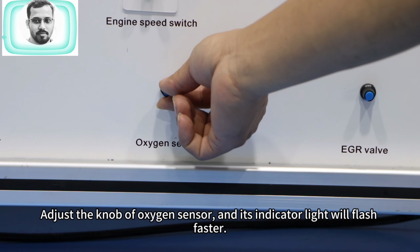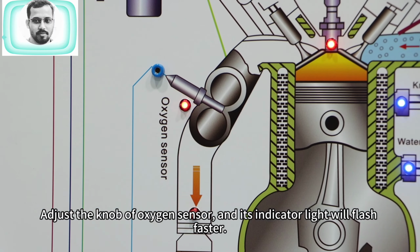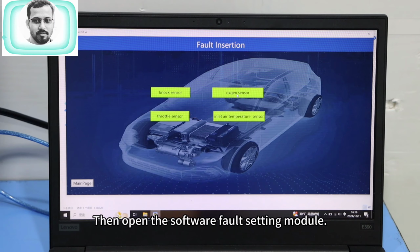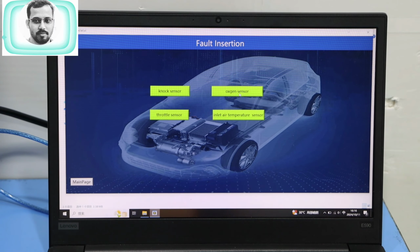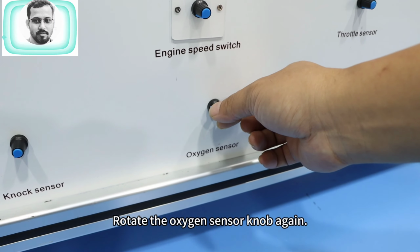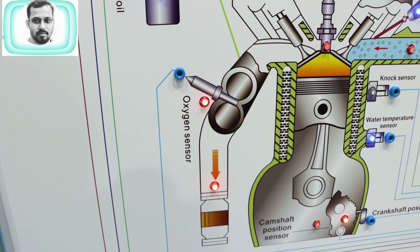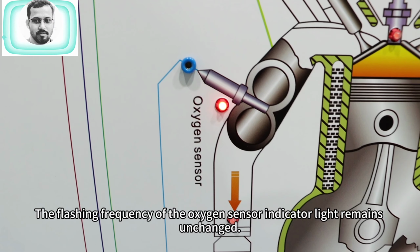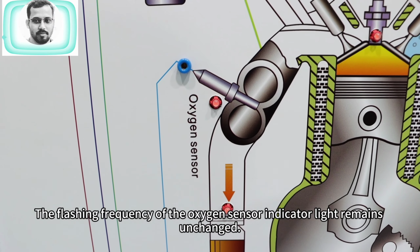Adjust the knob of the oxygen sensor and its indicator light will flash faster. Then open the software fault setting module. Set oxygen sensor fault. Rotate the oxygen sensor knob again. The flashing frequency of the oxygen sensor indicator light remains unchanged.